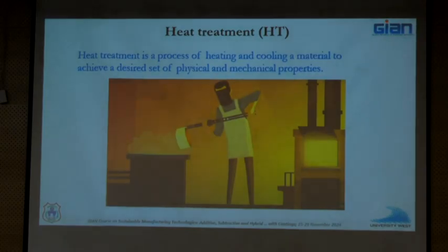AM itself is expensive. You don't want to combine it with HIP. And HIP also is a very sophisticated equipment. Most companies will not have HIP. They will send their parts out to some facility where it can be hipped. So hipping is to be avoided if your application allows you to avoid it, correct?